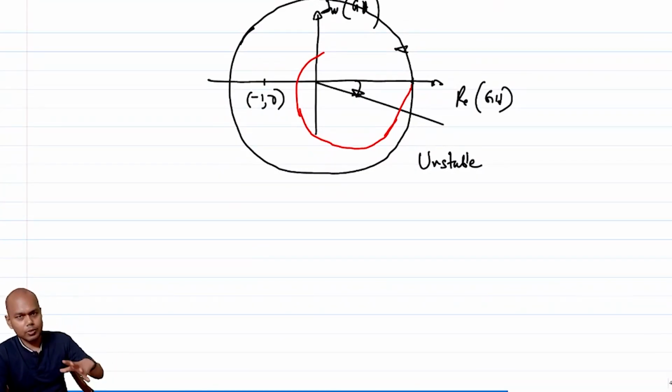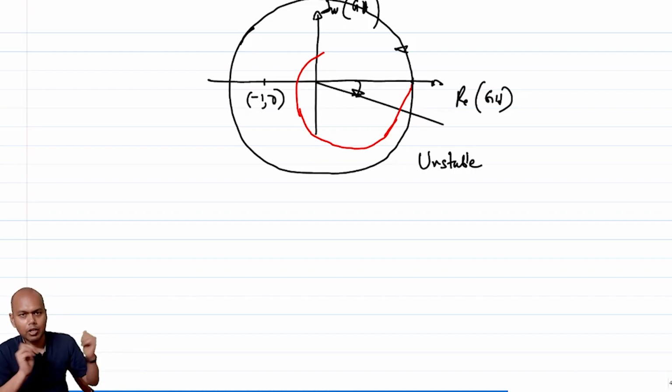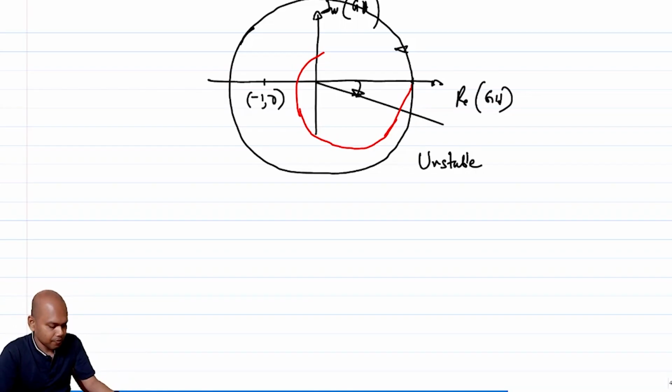If you are doing a transmitter, for example, then the reflections can land on top of the incident wave, and you can have large amplitudes, right? This is significant in a transmitter, because in a transmitter you are already sending out large signals. In a receiver, typically you are receiving very weak, feeble signals, but in a transmitter you are shouting at the top of your voice, and if the echo also comes back and increases the amplitude, then it can break the device.